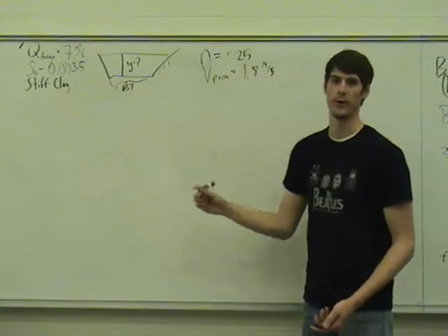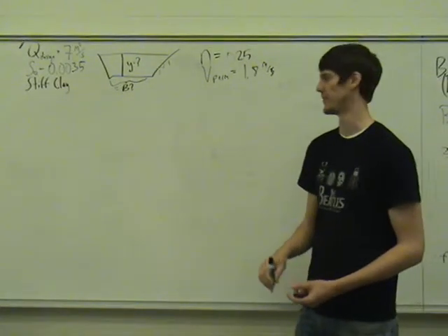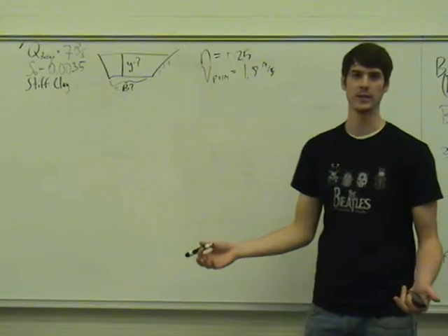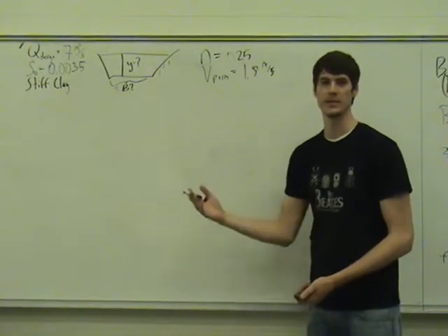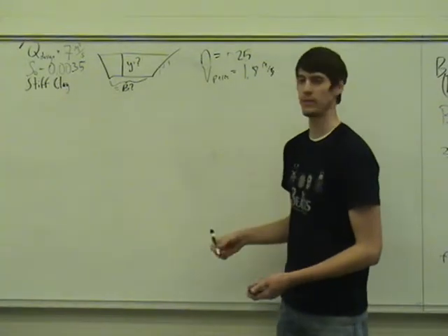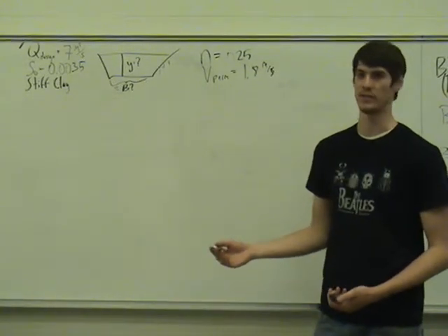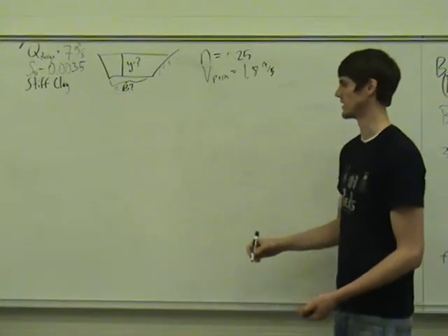And that's the maximum velocity that we can pass through the channel without the channel scouring. And then we want to consider sinuosity. Because this is a straight channel, there is none. And so the first step that we want to do is try to determine what the hydraulic radius is for this channel. And for that, we can use Manning's equation.